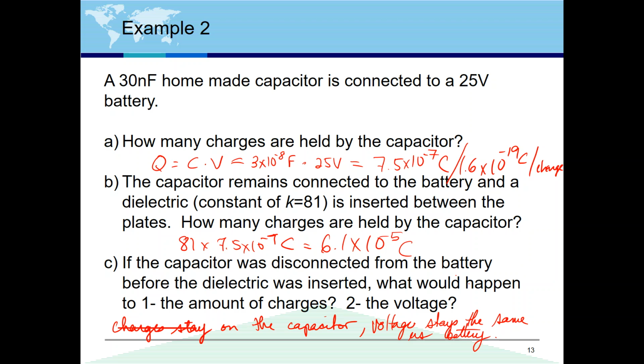To discharge, the same speed, instantaneously. Okay. When we do circuits, you can put a resistor between the battery and the capacitor. So here's your battery, and here's your resistor. And there you're doing something called an RC circuit. An RC circuit charges more slowly, and you can discharge it more slowly as well. But if there was no resistor there, instantaneous.